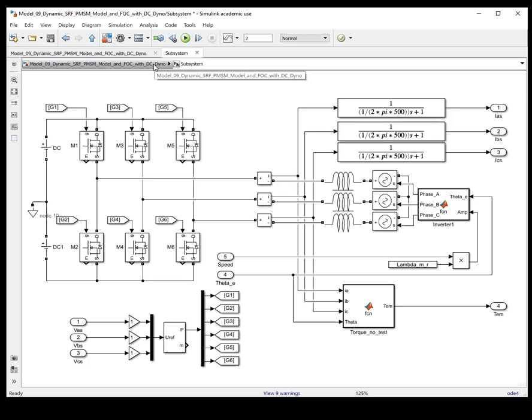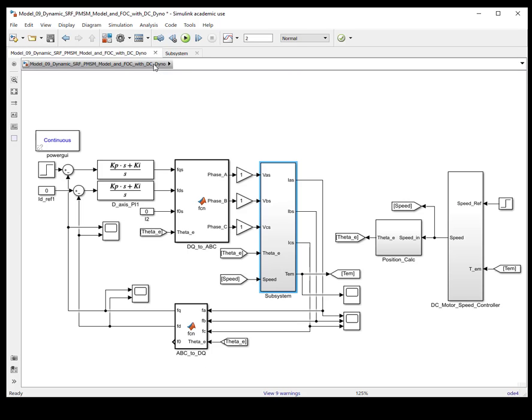Okay, so those are different variations that you can try, but I hope this helps you understand how to implement a three-phase inverter using MATLAB Simulink blocks, and now you have a comprehensive PMSM torque control model that uses current references to control torque, and then you have a dynamometer regulating speed at the other end.